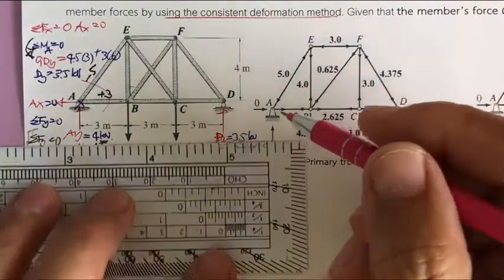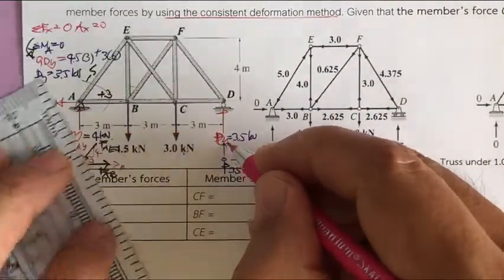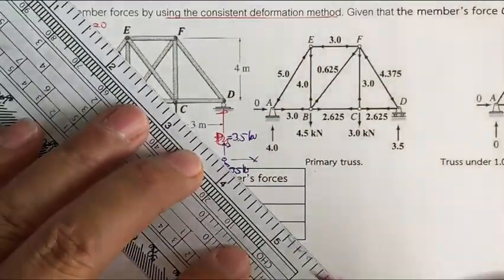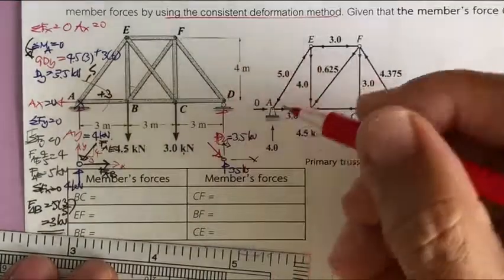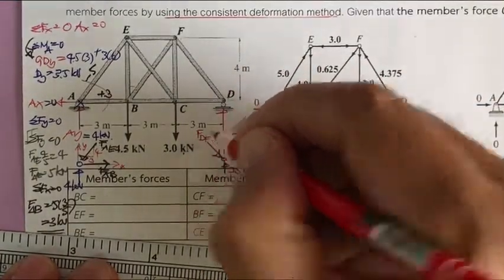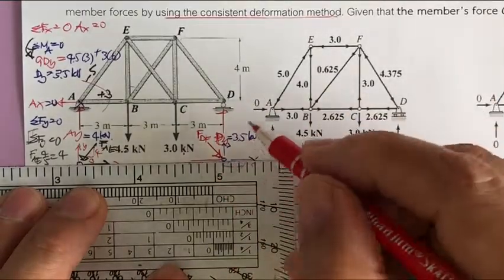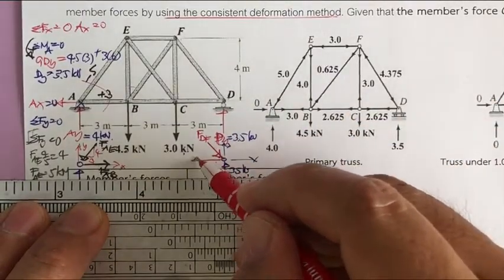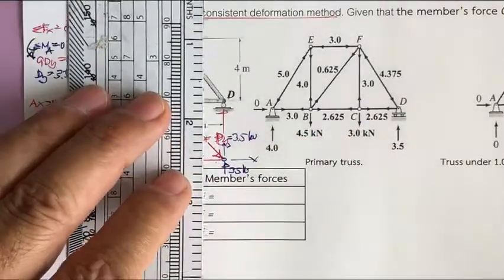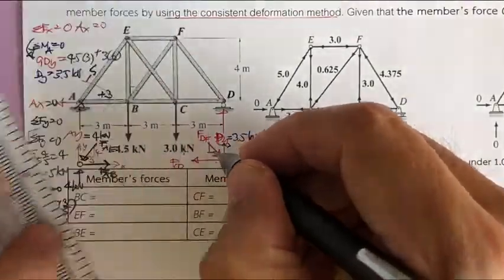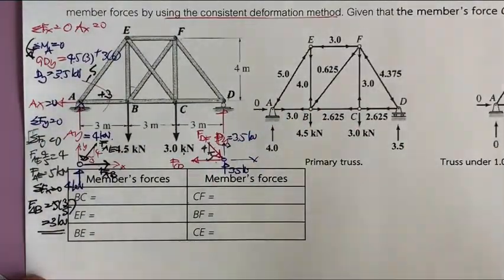Okay, and then you may have the x and you may have the y here, and for sure you will have the compression here, and the force is F sub DF, and this one also must be in tension because of this. Okay, this is going to be F sub CD, and again you can do the same calculation, and then you get the force in this member.